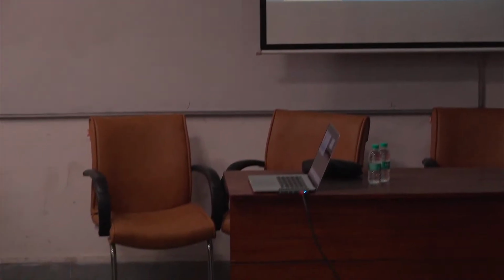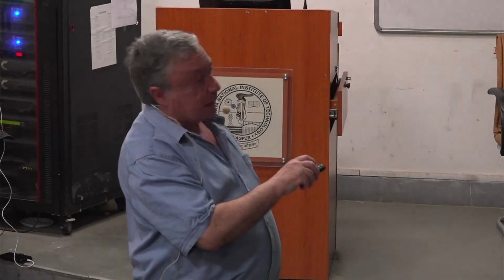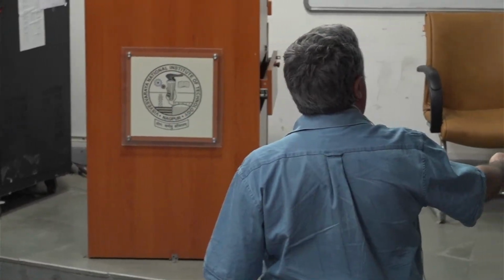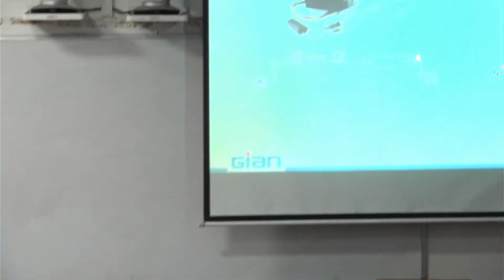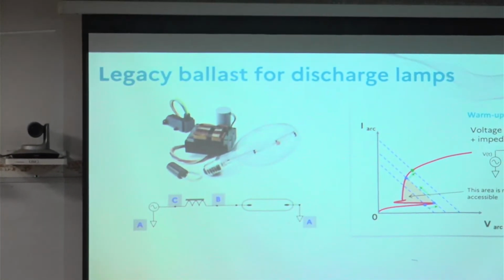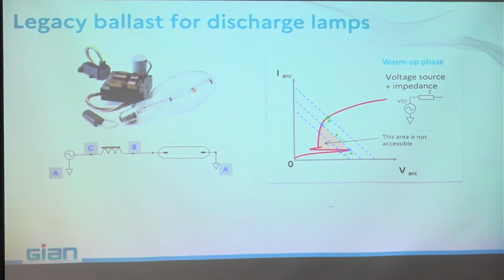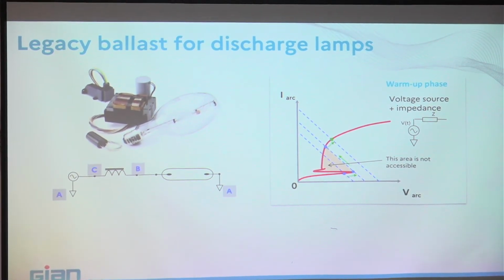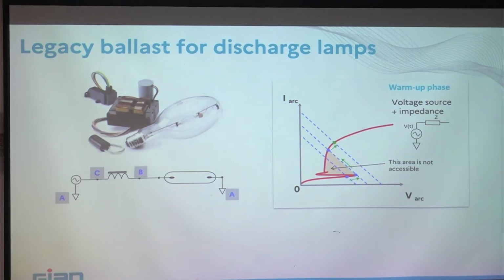You start the lamp, and you expect it to catch back the stable operating point after the end of the warm-up phase. And this is not good for the lamp, because if you leave the lamp alone here, you will damage mainly the electrodes inside. The electrodes will be treated very badly. You will have a vaporization of the material, and if you damage the electrodes, of course you change the geometry of the lamp for the acoustic resonance, what I was telling before, but also you will reduce the lifespan of the lamp.